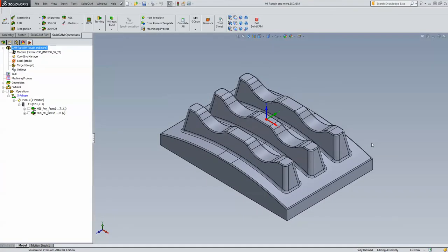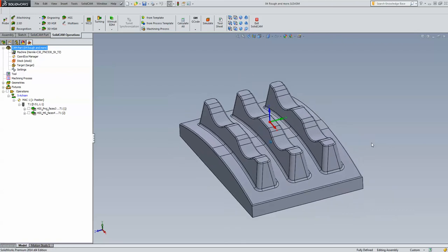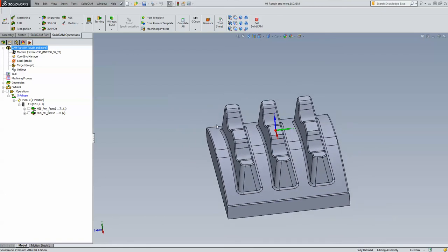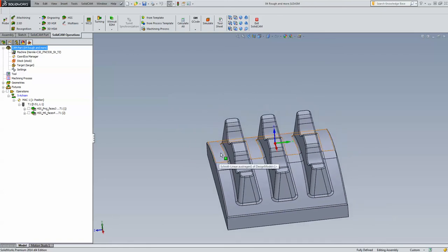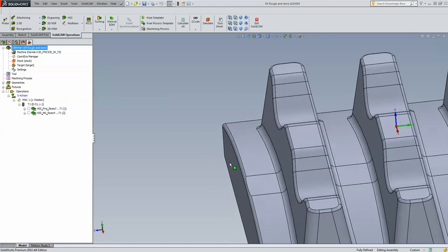inside HSS. Okay, now what I'd like to do is actually mill down on this area over here around this wall, but we have excess material around there. What happens if we have excess material around the wall? Well, what I'm going to do is as follows. I want my toolpath to just go projected according to this curve, to work exactly on this curve itself around the part. So if I were to go into the operation that I've created over here,